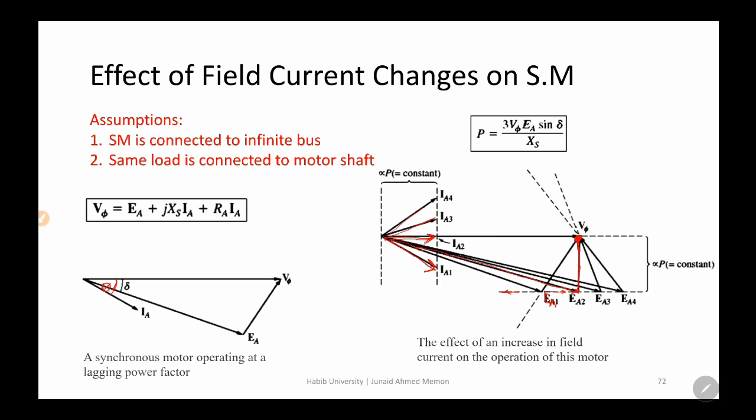But in the case of a synchronous motor, you have a device that is operating as a motor, but with the power factor of a capacitive load. It means if you have other motors, those induction motors, working at a lagging power factor, you can install one or two synchronous motors to do the power factor correction for the other induction motors, or other kinds of inductive loads. So that's a very interesting application.